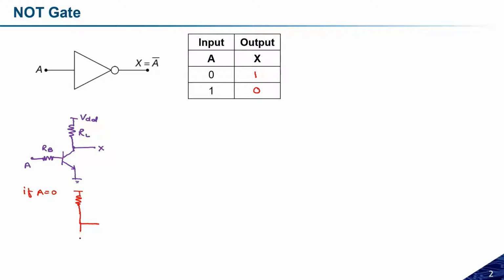We have an open switch and that will be grounded, and here we are observing X. Here I have a VDD, here I have an RL. Let us assume the voltage across this RL is VRL. So whatever X I will receive, the X will be VDD minus the voltage across this RL, meaning VRL. So this is what we have already studied before.